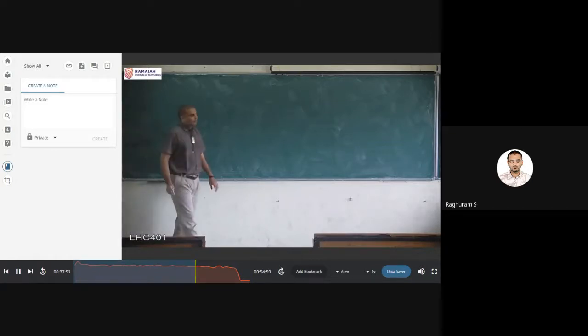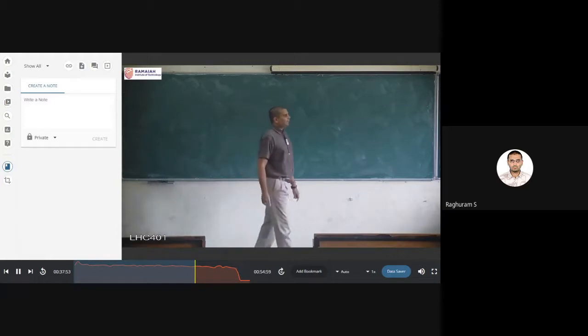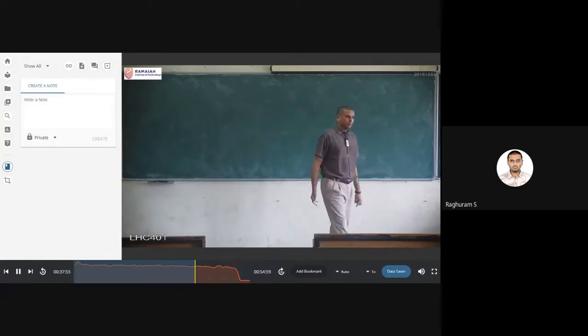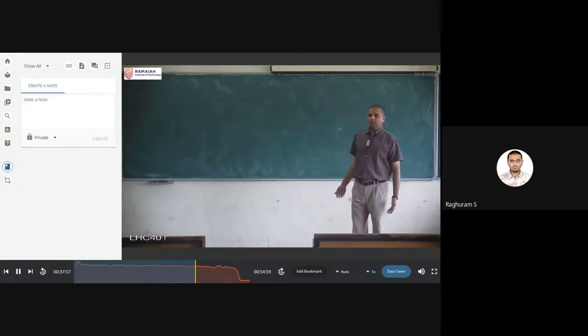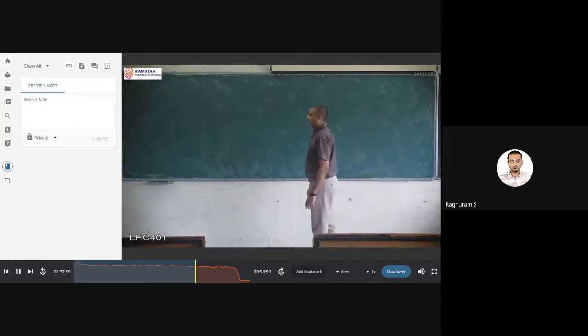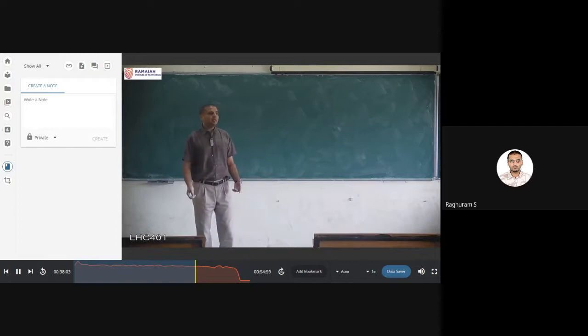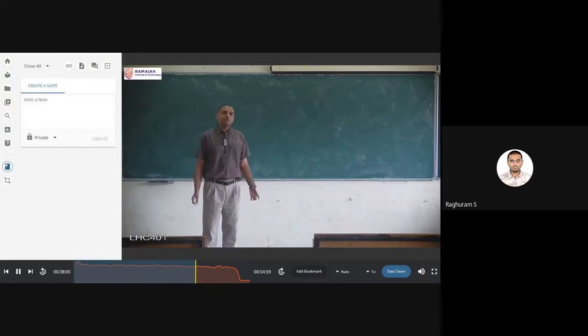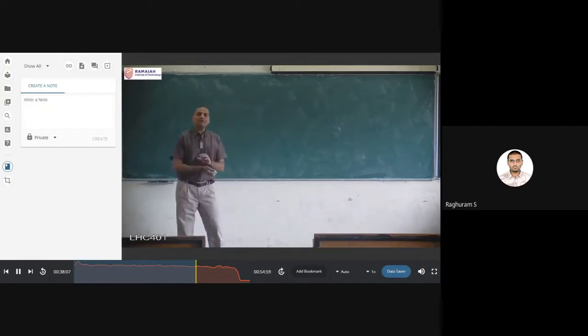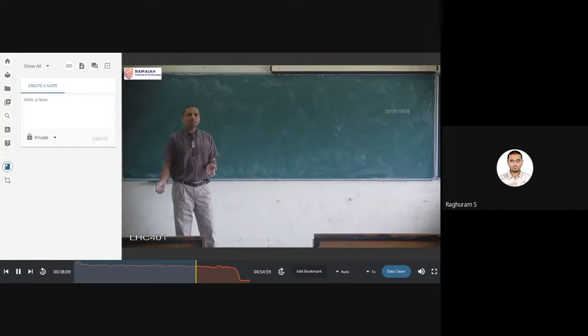Okay, so one question that is still pending: NMOS is somewhat okay, because we want positive voltages of Vg, but for a PMOS transistor, we want a negative voltage for Vg, but in the circuit we don't have that anywhere, right? We have only positive voltages, or we have zero. Zero is the most negative voltage. So how do we get around that?